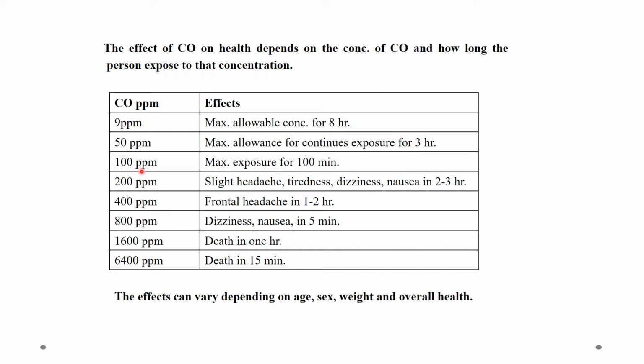If it is 100 ppm concentration, then the maximum exposure is 100 minutes. If it crosses 200 ppm, then it causes slight headache, tiredness, dizziness, nausea in 2 to 3 hours. If its concentration is 400 ppm, then it leads to some heavier headache in 1 to 2 hours. If its concentration is 800 ppm, then it causes dizziness, nausea in just 5 minutes.